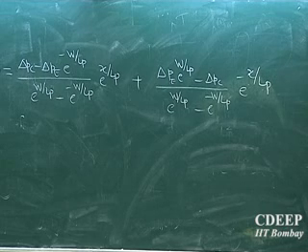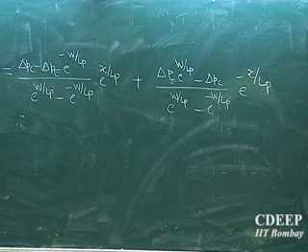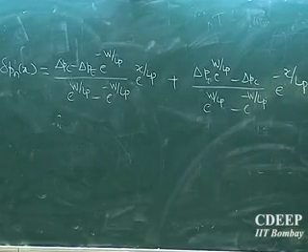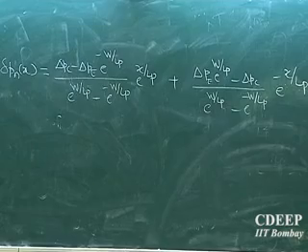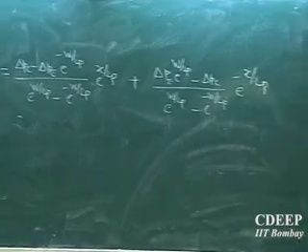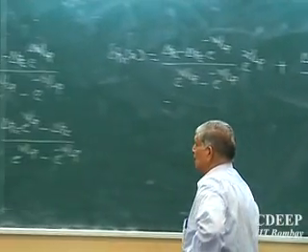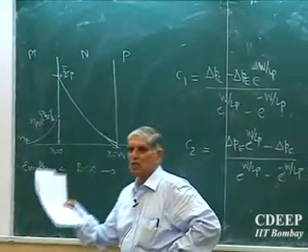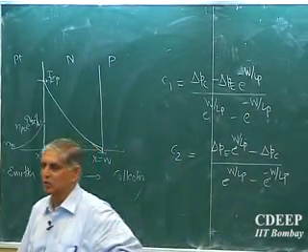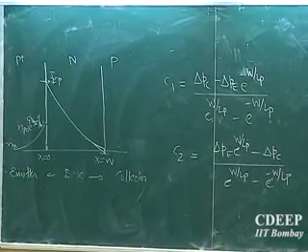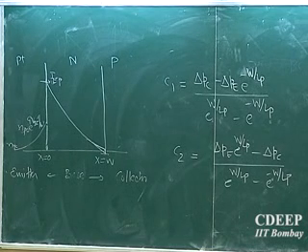And what will be that current? IEP. What is the current at x is equal to W? ICP, the current entering the collector. Is that correct? So I will be able to calculate collector current and emitter current from the whole profile in the base. Please remember, I keep saying earlier, in MOS transistors minorities hardly play a role, of course they do now, but in most theory which we did, we say minority currents are practically negligible and only the majority carrier transport occurs, drift transport.